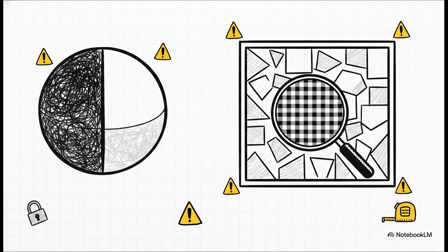Failing to assign a material to a geometry object will cause an immediate engine import failure. You must strictly separate transparent and opaque elements into different materials. You also need standardized naming like M_0_0. Furthermore, your UV layout needs a minimum of 80% space utilization and a uniform texel density, typically 1024 pixels per meter. This is completely non-negotiable for the QA team.